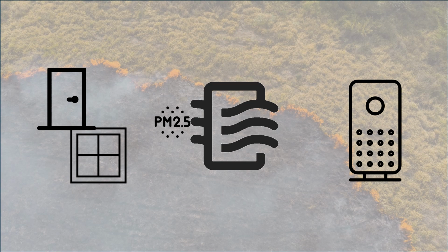So on the intake side, we may need to use good quality filters to check particulate matter from the smoke or traffic pollution. At the same time, we need to make sure the building is as airtight as possible. So as opposed to using doors and windows for natural ventilation, now we need to close windows and doors. Even so, since some of the poor quality outdoor air can get in, we may need to use portable air cleaners inside rooms.